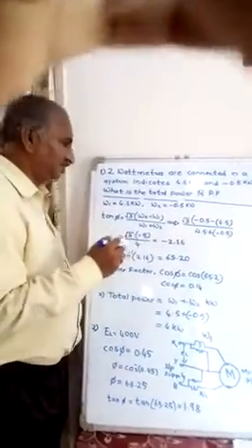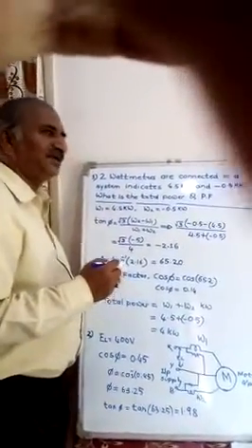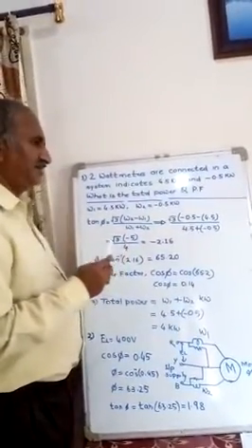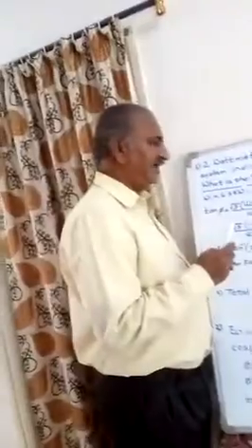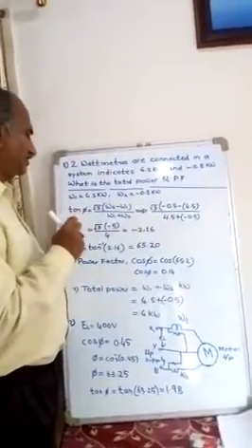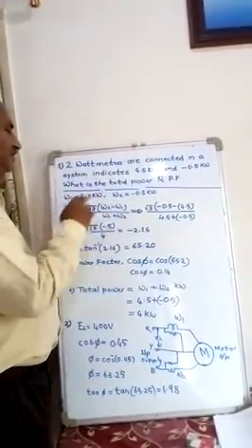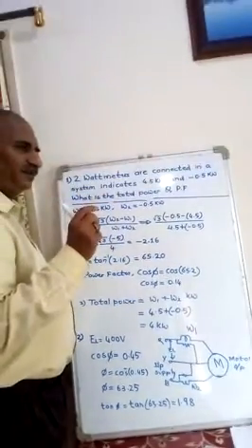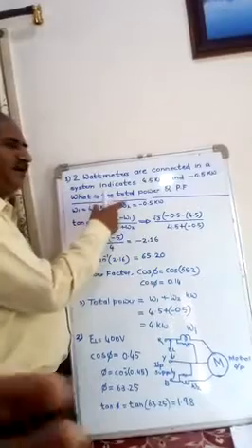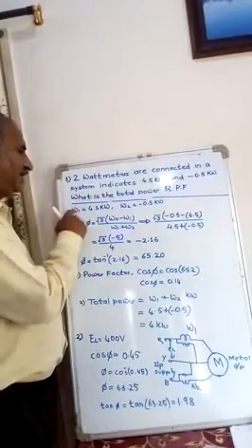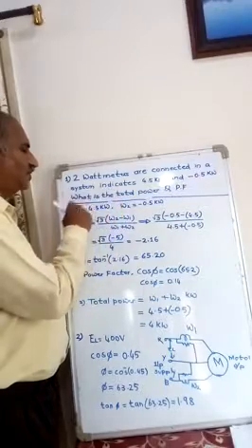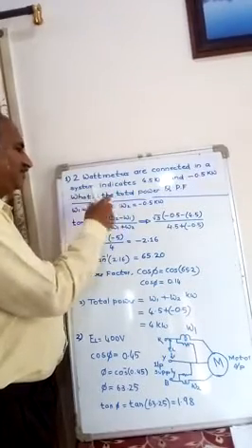Hello, good morning students. Yesterday we have seen the derivation of three-phase power, how the three-phase power can be measured. As per that, yesterday I told two important equations. One, total power equal to W1 plus W2. In two wattmeter method, we are having two wattmeters. Wattmeter reading 1 is W1, wattmeter reading 2 is W2. Total power equal to algebraic addition.